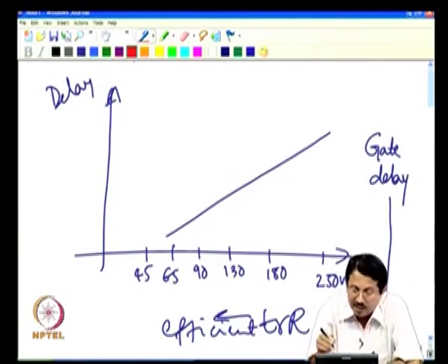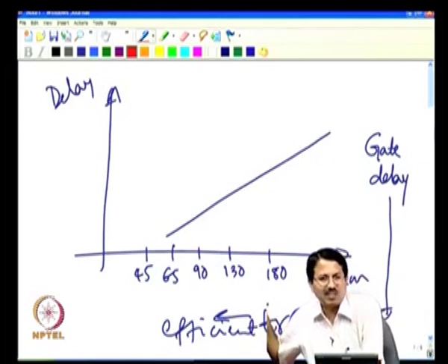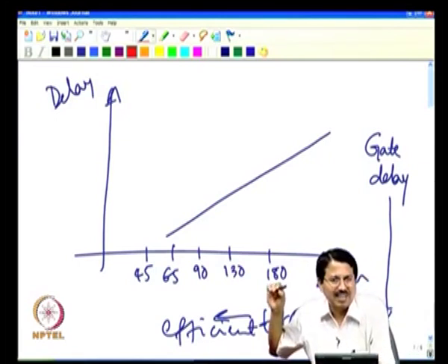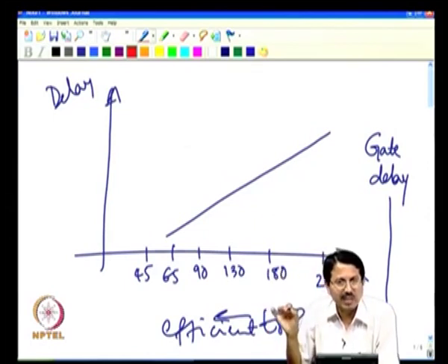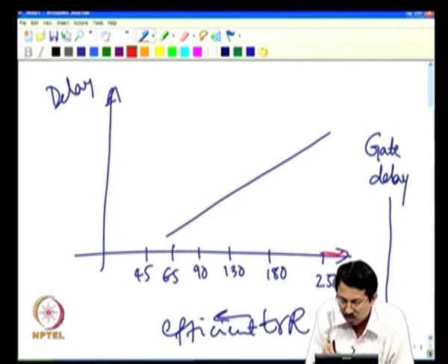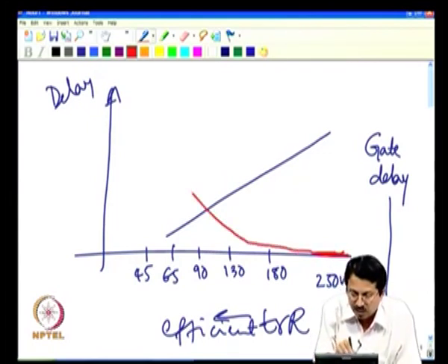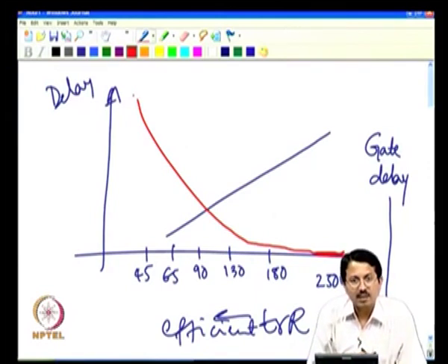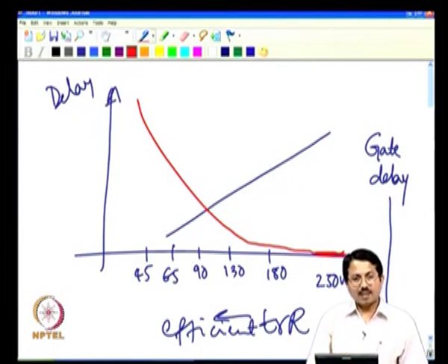So, if you were to look at interconnects in older generation technology, 250 nanometer and beyond, interconnects were an afterthought, you never bothered about interconnects. They are ideal metal lines, take signal from one location to the other location, they do not contribute any further delay. So, it was non-existent compared to gate delay, your interconnect delay was very low. But what has happened in the recent past is something like this. Your gate delays are increasing, your interconnect delays are increasing, and hence interconnects are becoming bottlenecks, right.